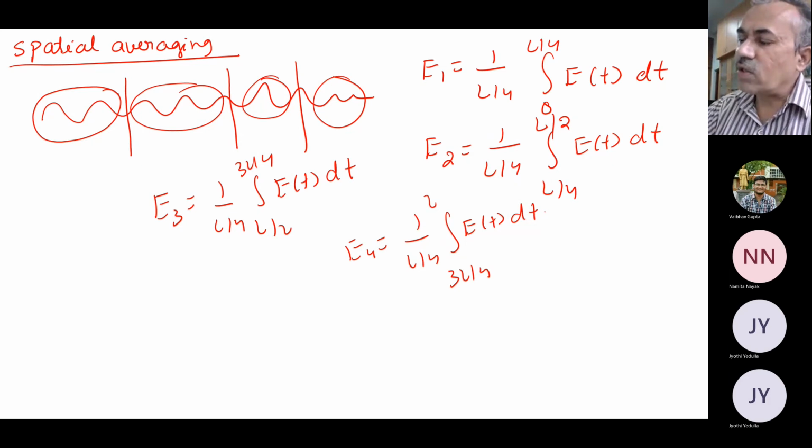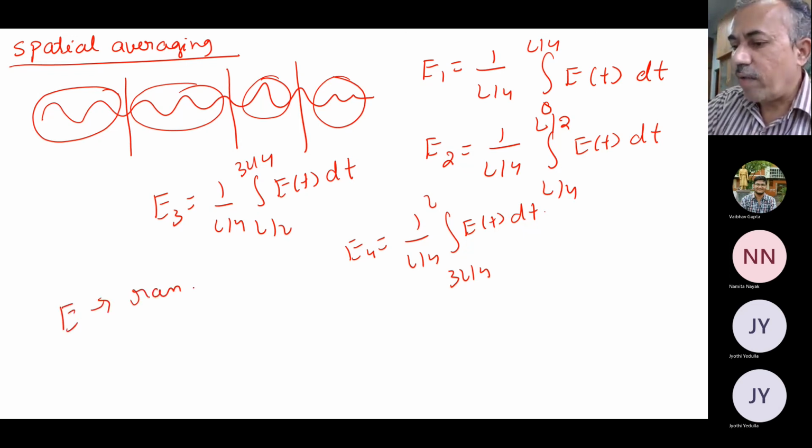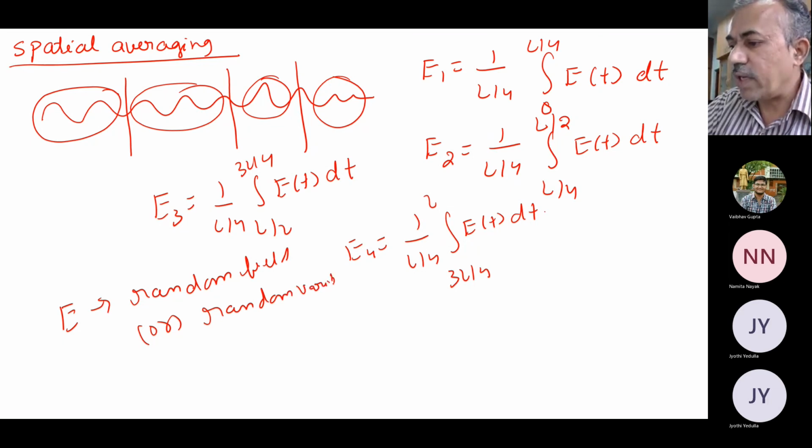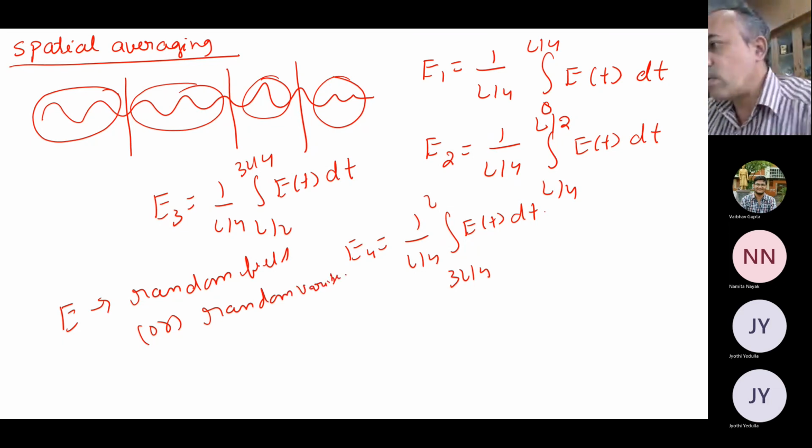Now there are other methods also to handle random fields, like the Karhunen-Loeve expansion and other kinds of techniques, but that requires a lot of mathematical background. Sometimes one has to decide whether Young's modulus should be modeled as a random field or a random variable, whether it is really required. There are many interesting things one can do while doing this stochastic FEM.